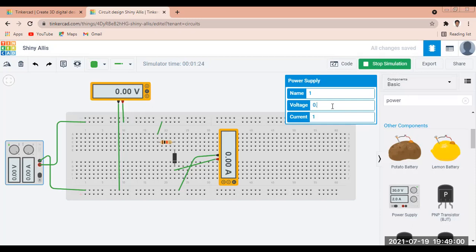When I give 0.6, I get a current of around 120 microampere, so that is the current just flowing. If I use 0.7, that's how it goes. Below 0.7, at 0.6, it was showing 0.